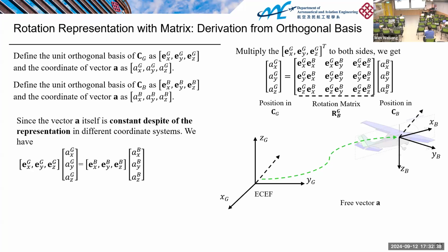You can just understand that roll, pitch, and yaw can also be represented with a 3x3 matrix. If you want to calculate the summation of rotations, for example, I rotate this with this, how do you summate this change of rotations? It's going to be the multiplication of the 3x3 matrices.